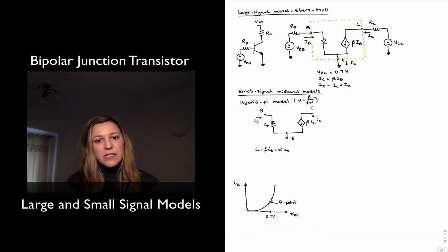It's a number that's approximately equal to 1. And this is going to be equal to the transconductance times the input voltage, and the input voltage is the voltage from base to emitter, V pi. So transconductance, we're going to represent as GM, letter G for conductance, and V pi.